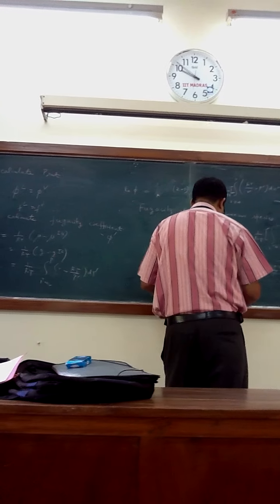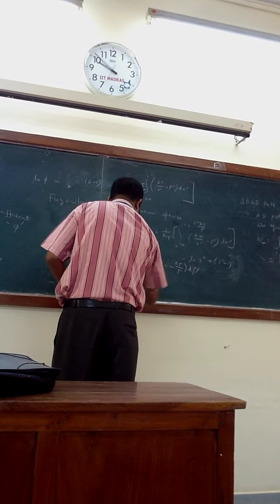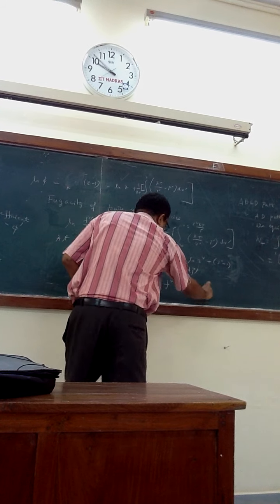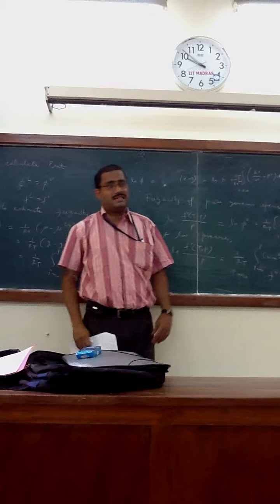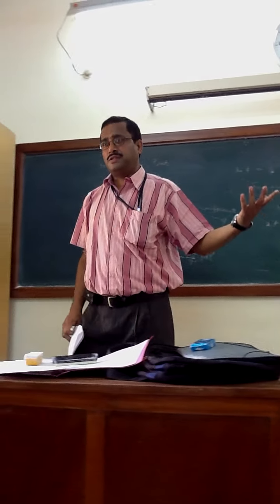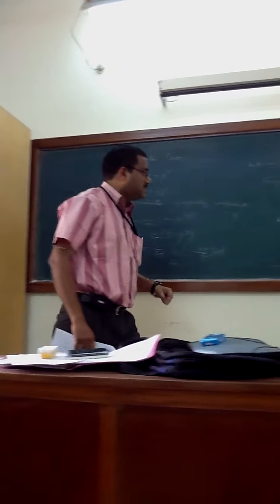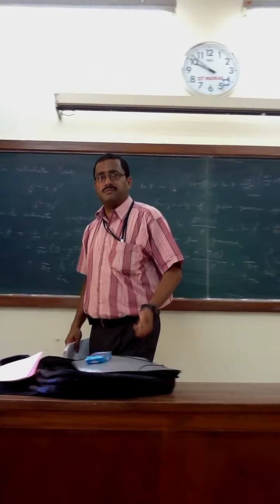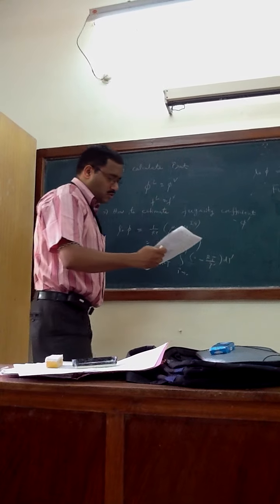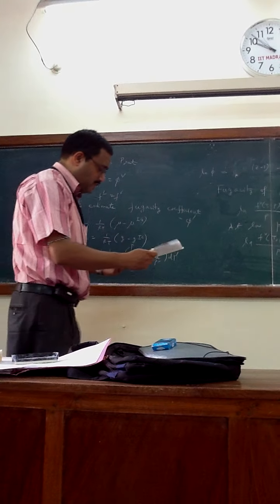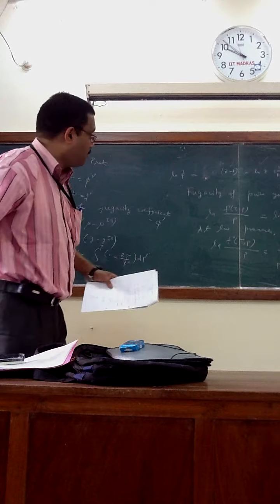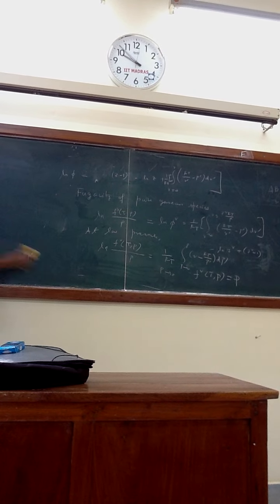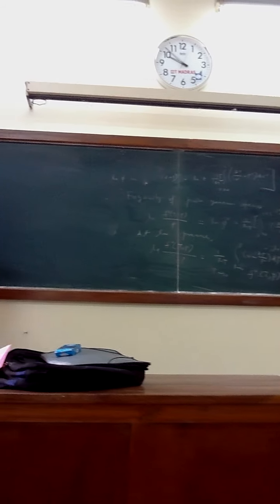And this f_V(T,P) at low pressure, at P tending to 0, can even be written as P. That's the basic definition of the fugacity coefficient. At P tending to 0, this integral will go to 0. e to the power 0 equals 1. So f equals pressure. Okay? So you can also have an expression in terms of the compressibility factor for the fugacity of the vapor. For liquid you cannot do much approximation.